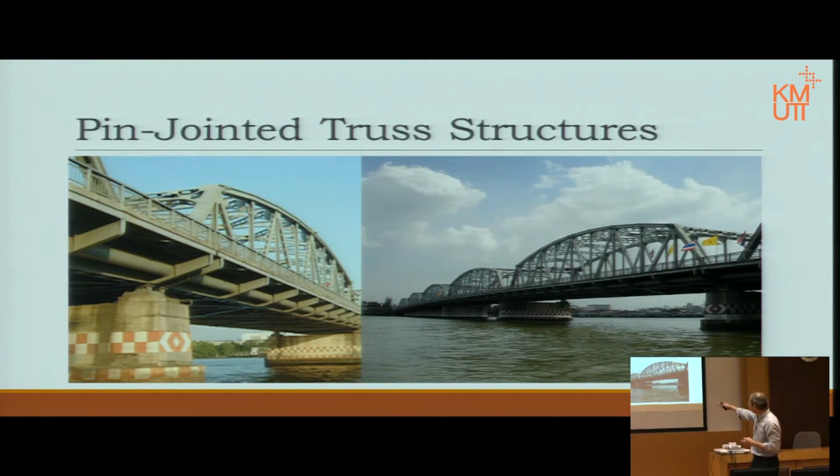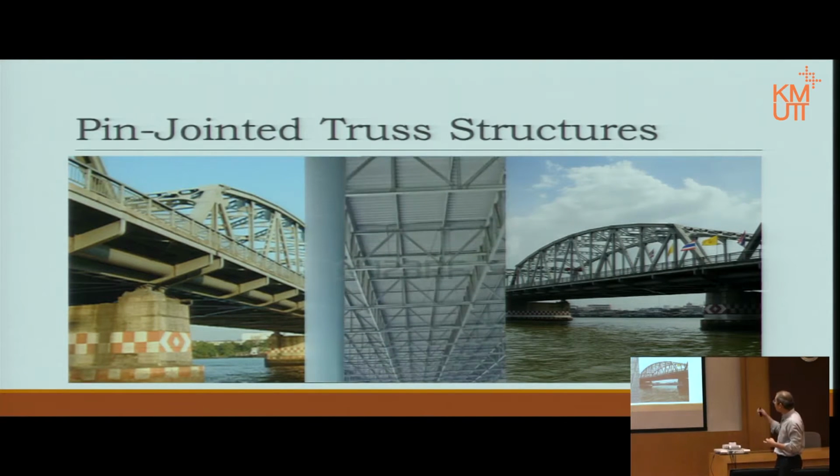Notice the framework from the floor. In fact, the beam or the floor hangs on that steel structure, which we call the pin joint truss, not the other way around. The pin joint truss is not supported by the beam. In fact, the pin joint truss supports the structure, and it transfers all the slab load and the beam load down to the columns. Sometimes this is a roof of a factory. This is also on the top there. You see the truss going around.